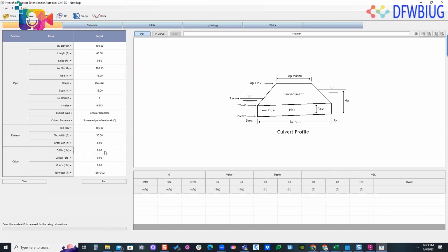And then you can type in what's the minimum Q coming into it. I said 5 is coming in, the max maybe 15 in increments of 1. Your tailwater conditions. If you're doing crown, normal, now you need to get with your engineer, how you're doing your calculations for your culverts. So I'm using DCT over 2. So I'm going to run it.